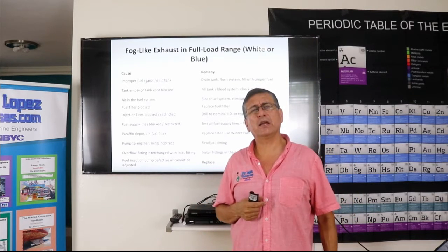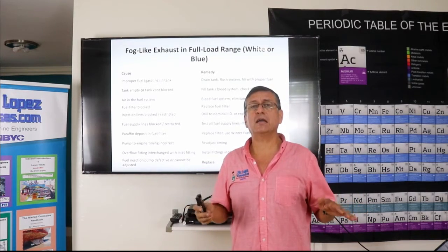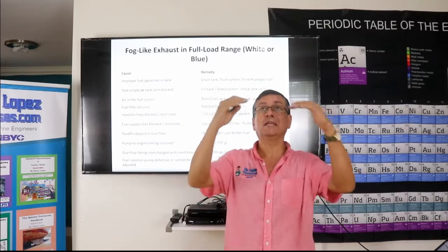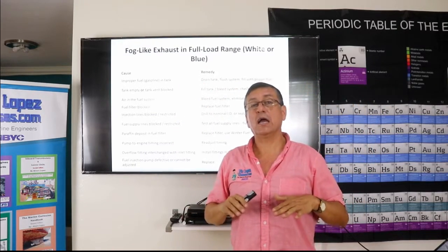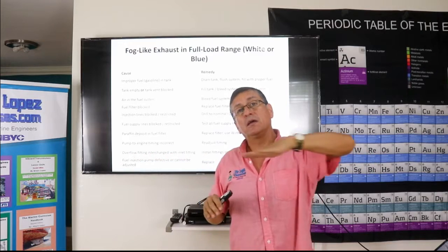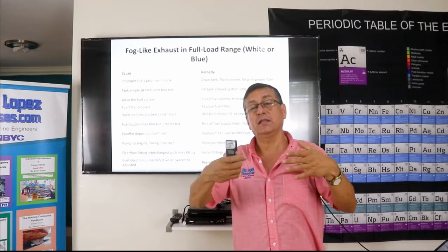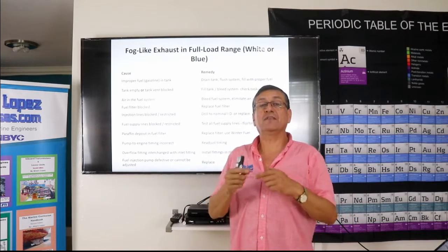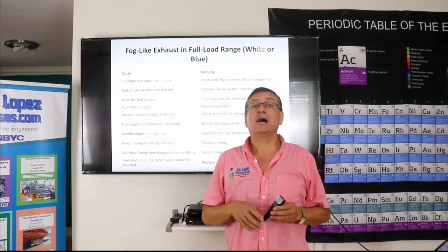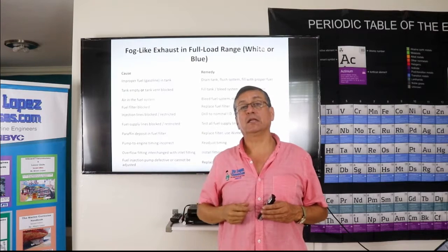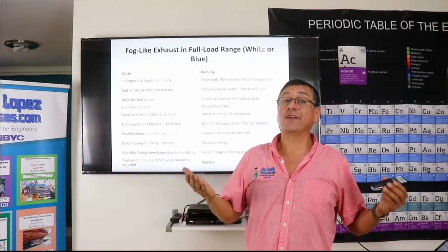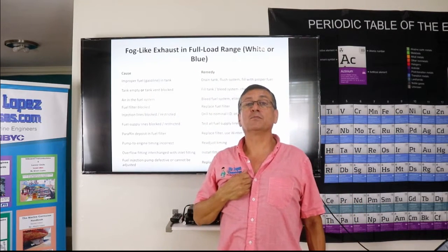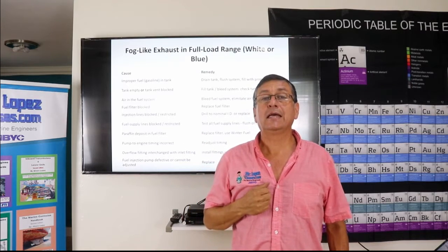How can the fresh water enter the tank? You remember, the tank is installed below the deck. If the deck has a water leak and the water accumulates on the surface of the tank, the water enters through the gasket of the flow switch and penetrates the tank. Or if the tank is corroded, with pitting corrosion, the moisture enters the tank and mixes with the fuel. Fresh water. And this is one of the possibilities for white smoke: water entering the combustion chamber.